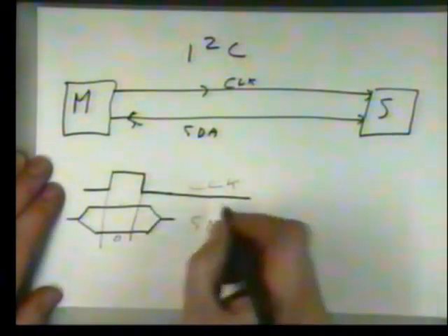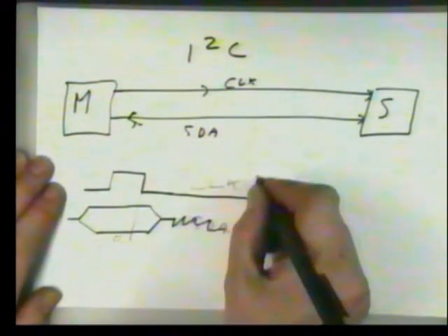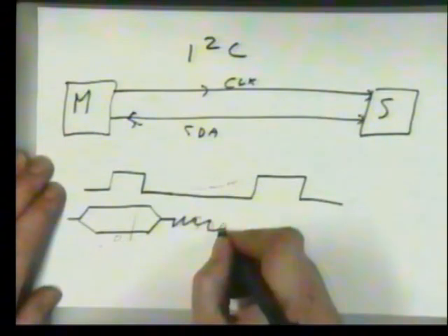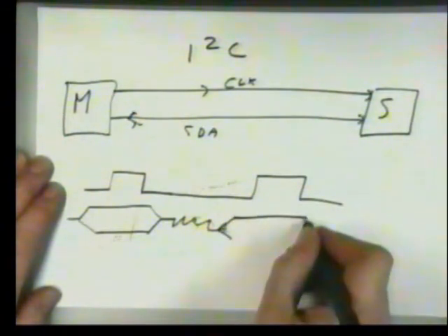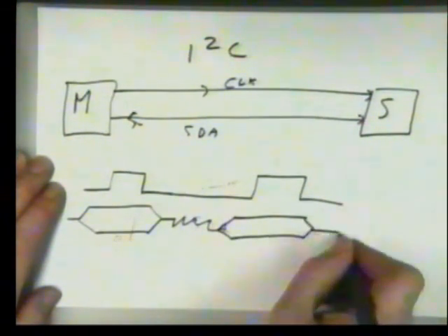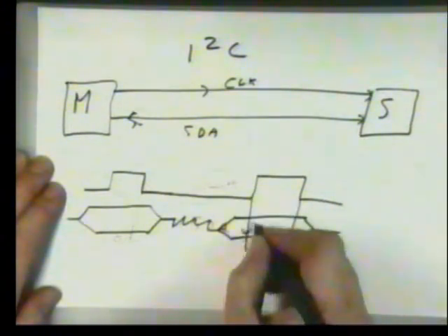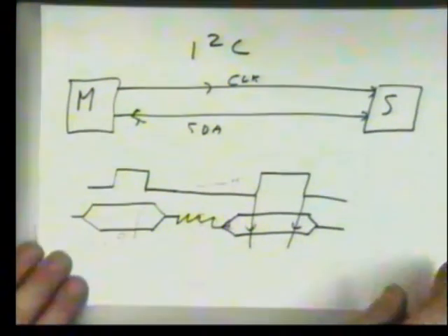And what you can do then, therefore, is while it's low, you can change the state, but when the clock goes high, it must have stabilized out. So the whole of the high period of the clock, it must be at a stable state. That is essential. So what we have is we've now defined the ability to transmit a logic 0 and a logic 1.